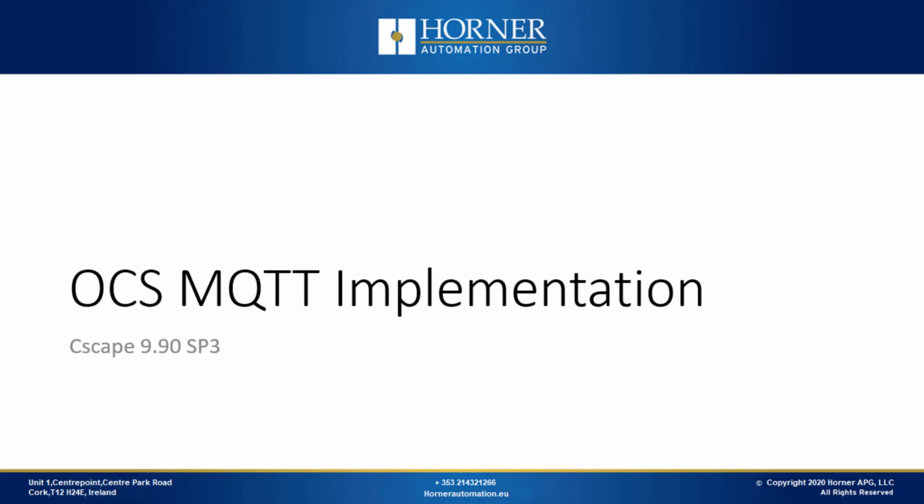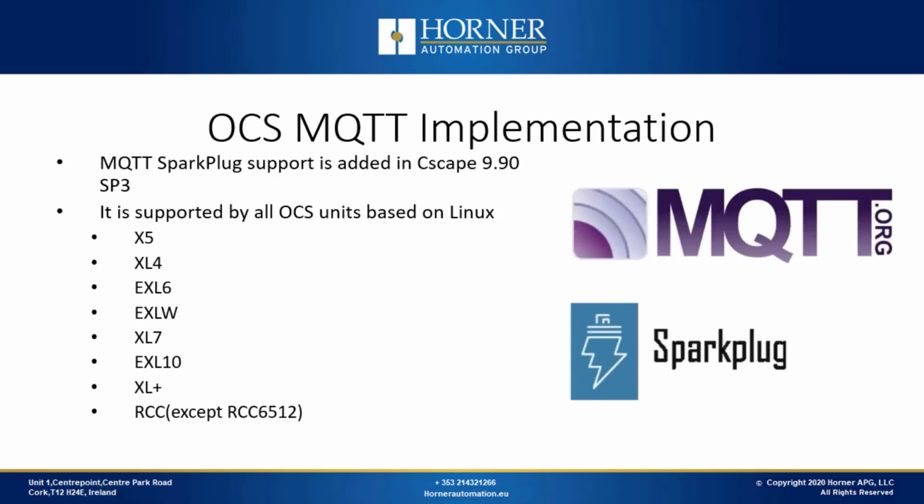Okay, so now let's talk about the implementation of MQTT in the OCS. We're adding Sparkplug support in Cscape 9.9 Service Pack 3. It will be supported by all operating systems which are based off of Linux, and there's a list here for reference. There will also be a firmware update required to 1540.